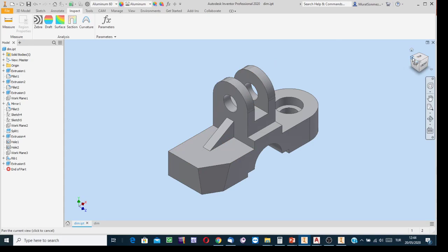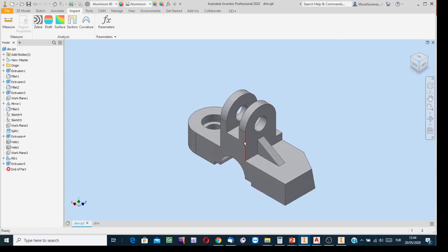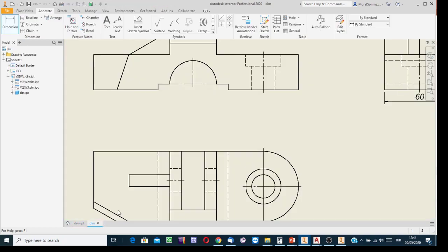The rest is the edge of this surface, the projection of this intersection, and the boundary of this part of the surface. So, although on the projection we have a single line, that line partially corresponds to the images of different things. So if your purpose is to indicate the dimension from here to there, then you must indicate the terminal points from here to there.